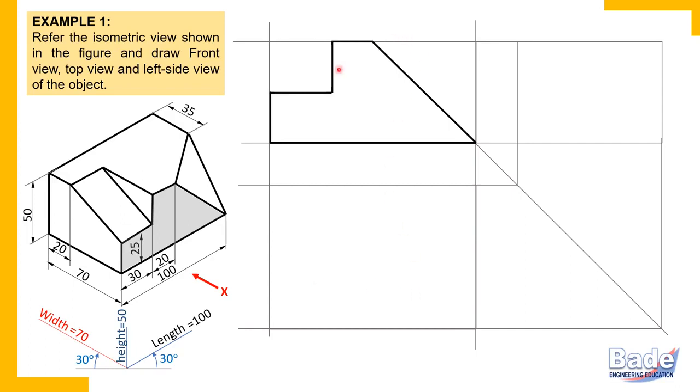So this surface between end projectors, whatever length of this surface from its left end to the right end, from these two ends you should visualize projectors. The same length of the surface will appear in the top view, and this surface is a line in the top view. So between these two end projectors, I have drawn that line, and that line is on the front.